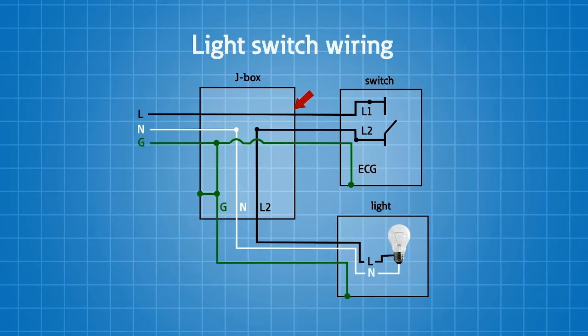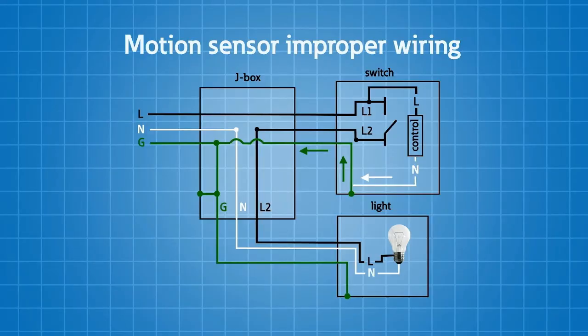We brought one set of conductors, and that was our hot conductor. And we brought an equipment grounding conductor as well. And we did not bring a neutral. When we had a standard light switch, that was perfectly fine because we're just breaking one conductor. But when you install a product like a motion sensor switch, which needs to have power, you need a neutral conductor to provide the potential voltage to power up electronics. If I opened up a light switch and I don't have that neutral conductor there, I could get that power by taking hot to ground, the equipment grounding conductor, to power up that unit, and it would work.